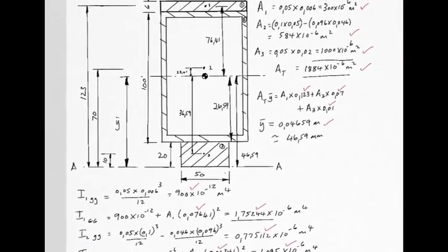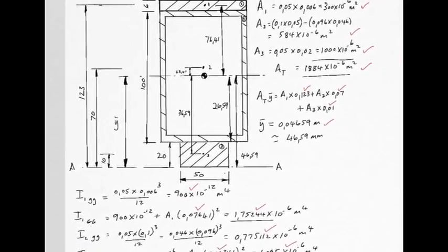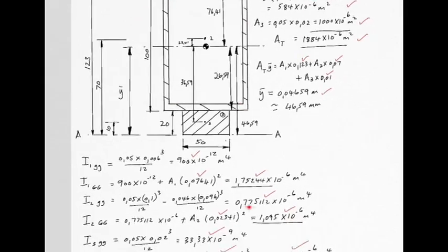Okay, its own second moment of area is the full rectangle, BD cubed over 12, minus the missing rectangle. So it's the full outer rectangle, as though everything was solid inside, minus the bit that is not there. Here it is here. Check your sizes. We've discussed them already with the areas, the 50 millimeters and then the 46 by 96 for the missing piece. We've done that already over here, and you get an answer.